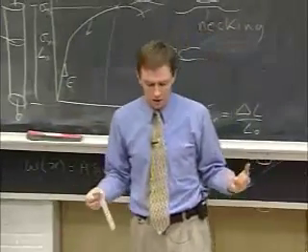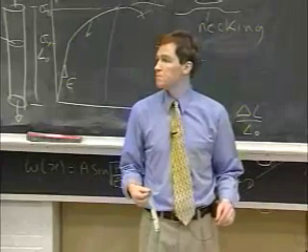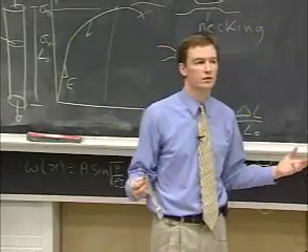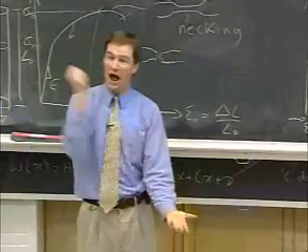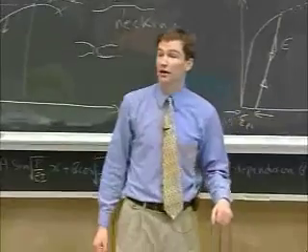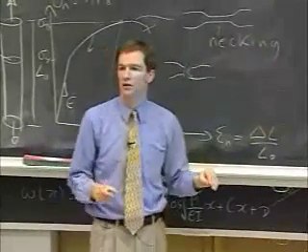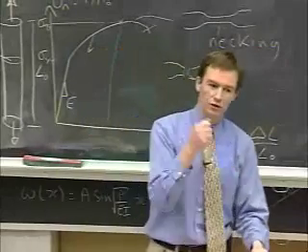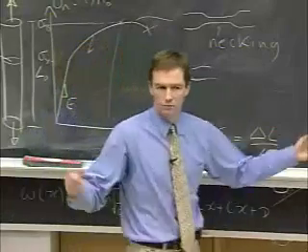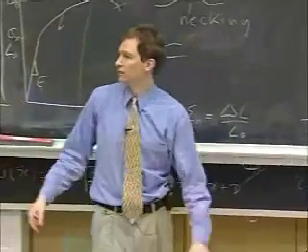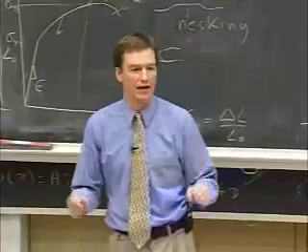How else might you do work hardening? Who are the first metal workers? Blacksmiths. When you hit things, what you're doing, whacking the metal, is increasing its strength. You're turning it into a shape, sure, but the difference between doing it hot and doing it cold we'll understand in a few lectures' time, but hitting it whilst it's cold will push up the strength. Obviously, there's a trade-off. You don't want to make it so brittle that it shatters if the horse gallops its foot onto a stone. But that's the blacksmith's art.